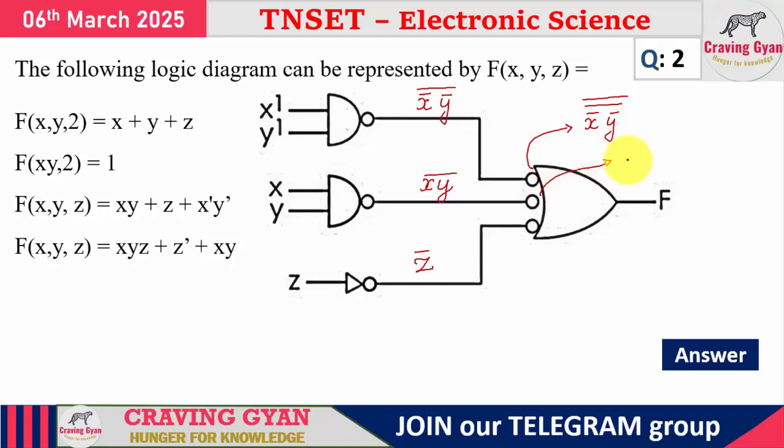Here what is the output? x into y, whole bar. Again for this negation you get a double complement. And what is the output at this end? We get z double bar. So these three things you need to add, since we are making use of an OR gate, we are making a logical addition. So f will be equal to, the double complements getting cancelled, x bar into y bar plus x into y plus z.